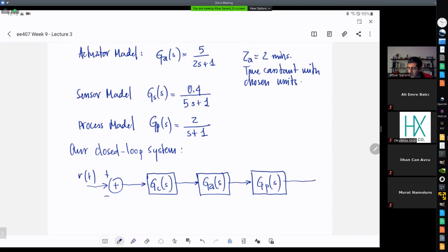The output occurs, okay? So this is usually known as the actuator signal. This is the plant input. This is our error signal. So this is our process variable, Y(t), often known as process variable or the controlled variable. Okay? And then the output is measured, but this is through our sensor model, GS of S. And that gives the comparator signal.